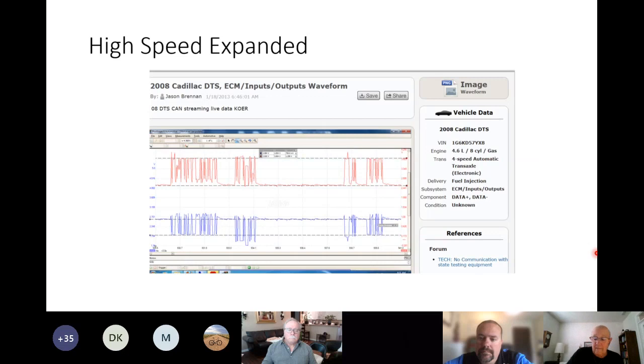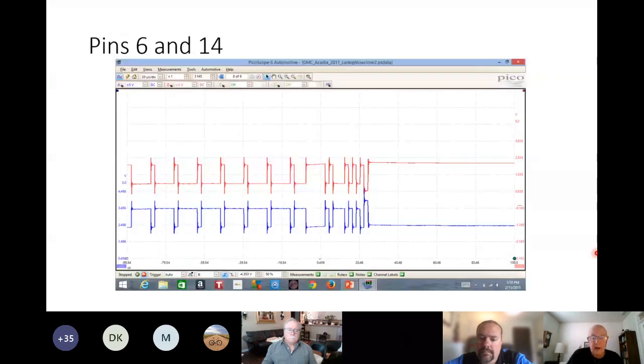Teaching the student to look for the mirror image is an important concept. This is where you need the 2-channel oscilloscope. You don't need 4, you don't need 6, you don't need 8, and some of these oscilloscopes are way more fancy than you really need. But by the same token, you can't do this with a U-scope, because you only have one single channel. You can't put 2 U-scopes on top of one another, because you will never get the time base to be exactly the same, and as a result, it won't look like a mirror image. You've got to use a dual trace, and a dual trace will give you the right information. Okay, good or bad.